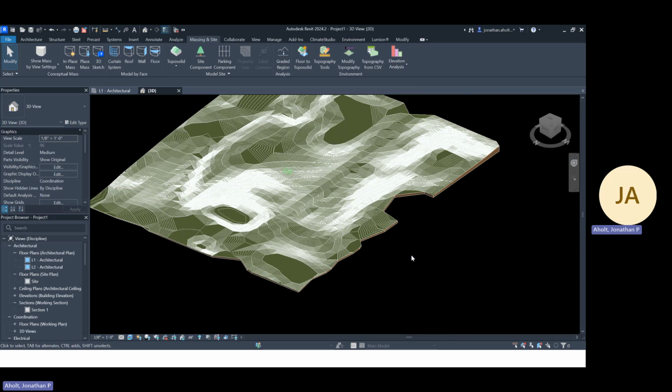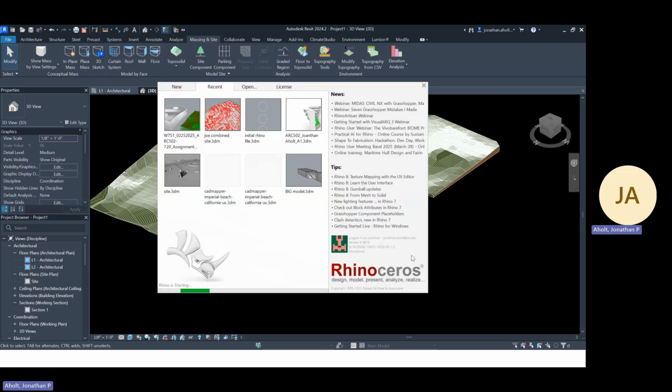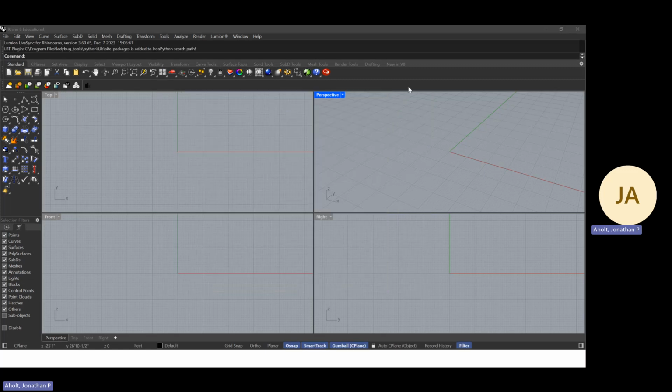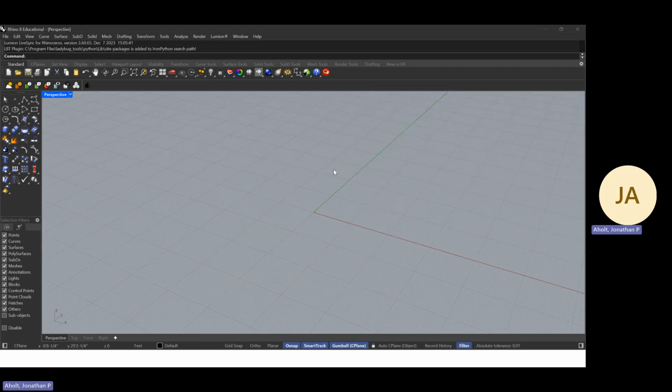It'll allow you to import the AutoCAD and then create a surface out of it by using some commands to basically connect each of the lines individually, and it will create a smoother project, and you can then import that into your Revit.